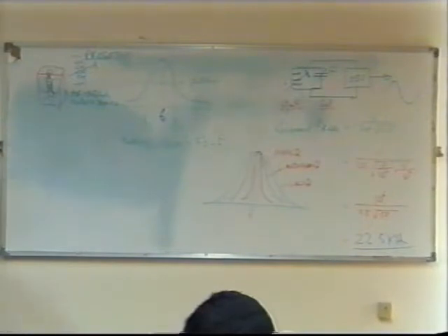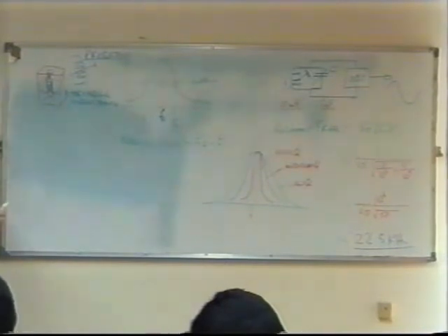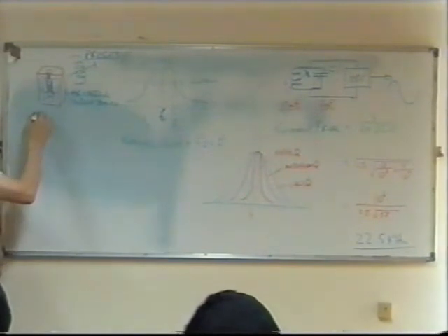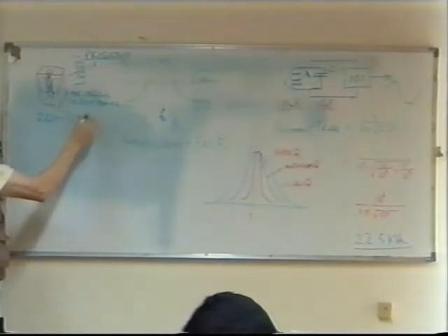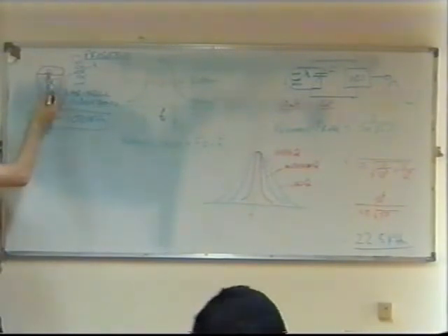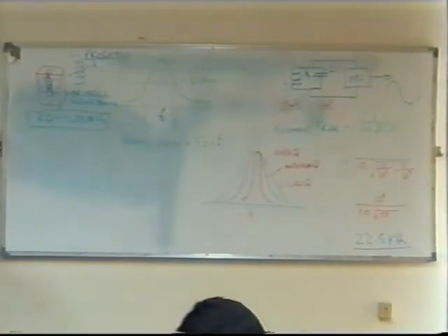And they would be handling frequencies up to about, what's the first RF of the aerotron? 10.7 megs. So up to about 20, between 20 and perhaps a maximum of 100 megs, maybe. And lower than that, just use more windings on the coil. But what about when we want to generate frequencies, say we want to design an oscillator for, say, microwaves?